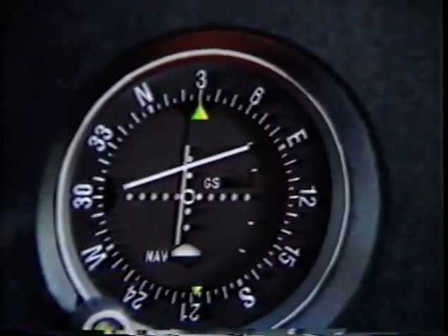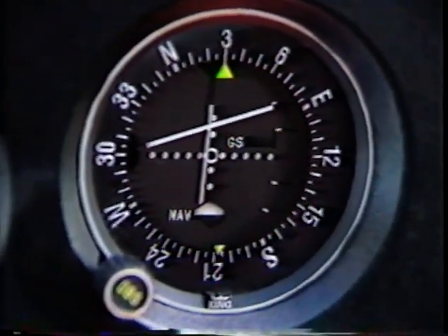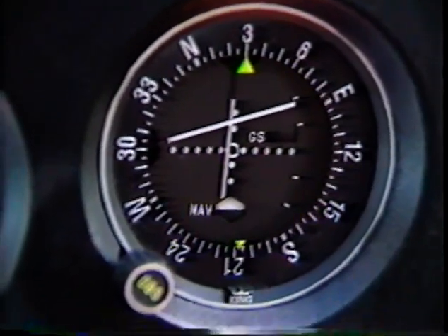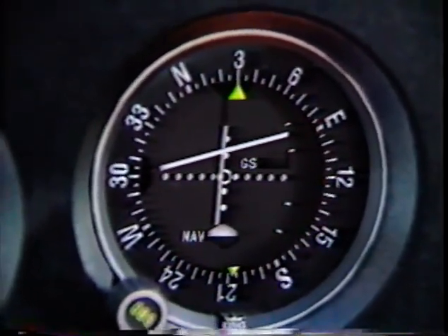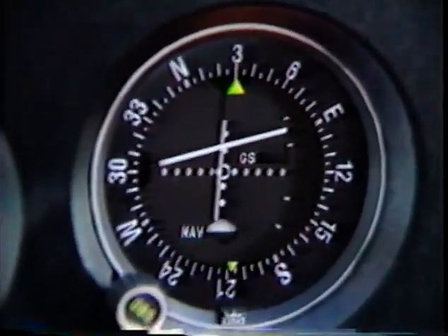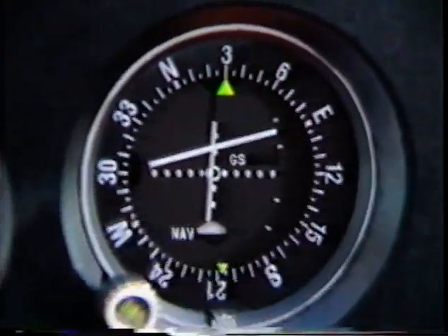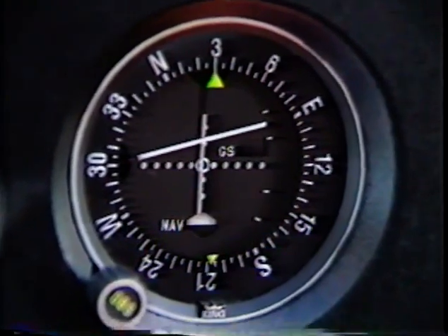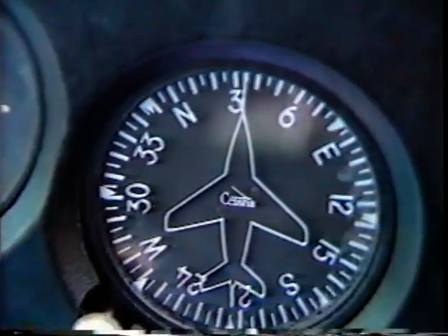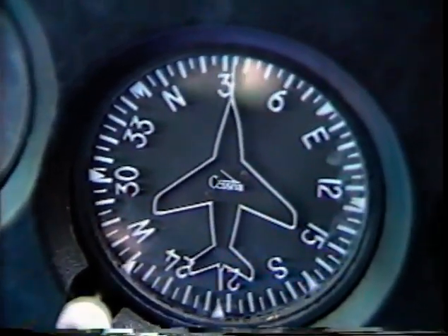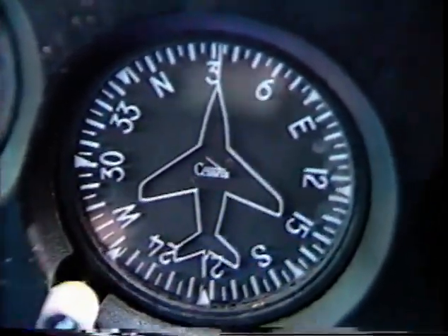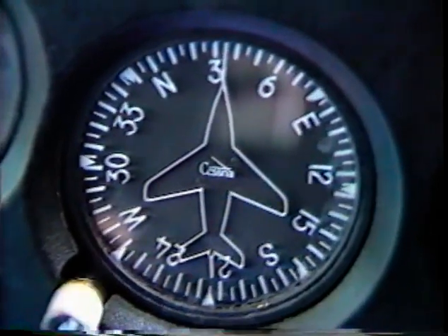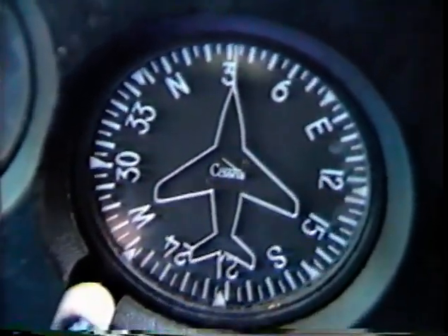As the aircraft starts to intercept the localizer, the CDI will move from full-scale deflection towards the center. As soon as the needle moves, begin turning the airplane toward the final course, assuming approach clearance has been received. When the CDI stops moving, stop turning. The DG now shows the first approximation to the reference heading. If the needle moves slightly, turn 5 degrees toward the movement. Continue bracketing with smaller turns until it stops completely.